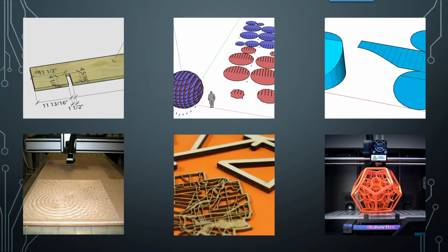Okay, so that's what you can do in SketchUp, and then the different stages of planning, whether you plan cuts and measure things, whether you slice things up in the software so that you can easily fabricate them, or whether you unfold things, that can all be done in the software. So that is a really great way to make things easy. If you're a sheet metal fabricator, you can go from a 3D piece to an unfolded shape very, very quickly, and then have it cut, basically.